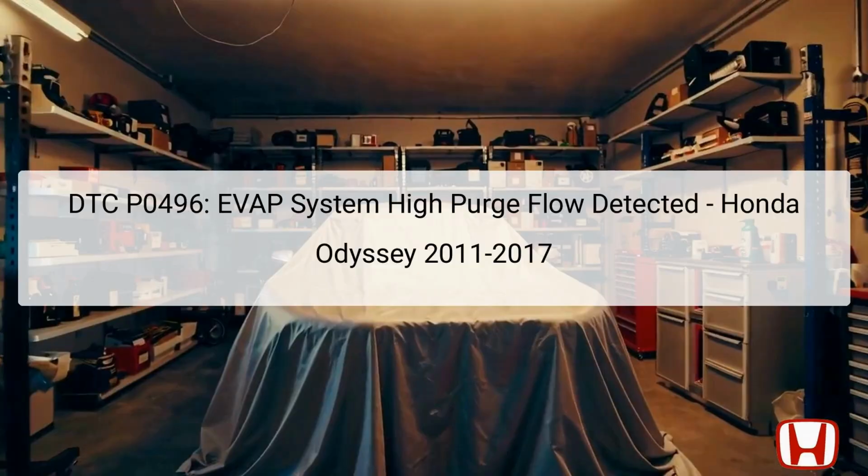The Diagnostic Trouble Code P0496 indicates a condition in the evaporative emission control system, specifically denoting that a high purge flow has been detected. The evaporative emission system is essential for capturing unwanted fuel vapors from the fuel tank and routing them to the engine for combustion, thus helping to reduce pollution and improve fuel efficiency.